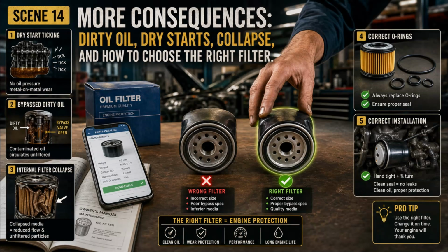In extreme cases, the wrong filter can even collapse internally, meaning the filter media or center tube deforms because the oil flow and pressure conditions are wrong. This is not common with a correct quality filter used properly, but it is one more reason not to gamble. So how do you choose the right filter? Start with the owner's manual. Most manufacturers specify the correct oil filter part number, oil type, and oil capacity. If the manual gives you an OEM filter number, OEM means original equipment manufacturer, the part specification used by the vehicle manufacturer or its supplier.